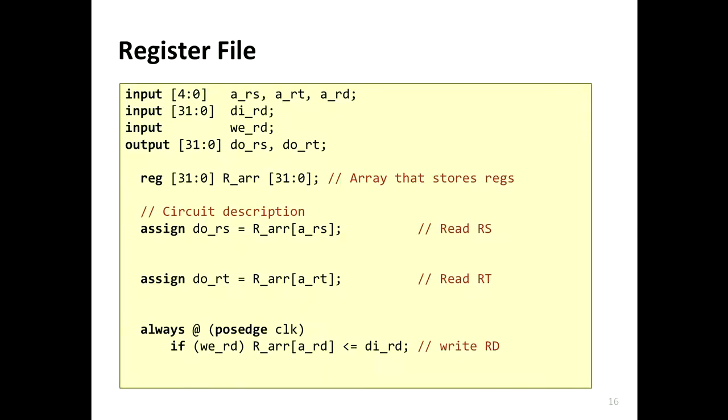And for write, you always have a clock. So this is pretty much the convention. You call this memory asynchronous read, synchronous write. There are, of course, synchronous read and write. Typically, you don't have asynchronous read and write. So there are different types of memories.